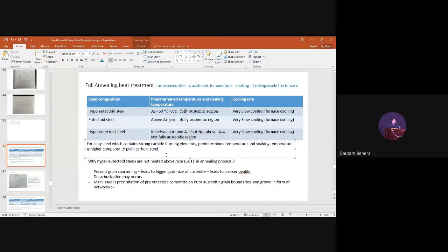I think this one I have told you while we were discussing the different variables of heat treatment. Sir, vanadium, niobium. Yes, very good. Vanadium and niobium. Excellent. Basically, vanadium and niobium form very strong carbides, and the melting point is above 1000 degrees, nearly above 1050. I don't exactly remember, but as I remember, it is above 1050 degrees centigrade melting point, right?